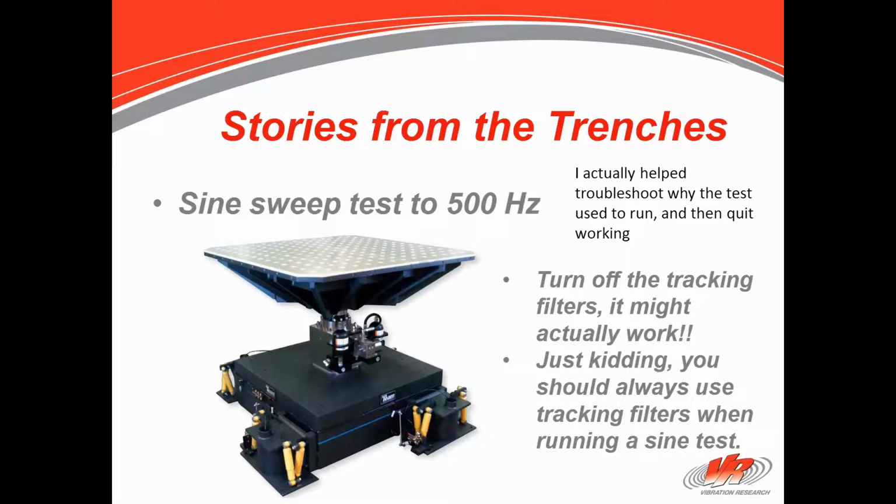So we talked about, well, how's your accelerometer mounted? Where is it? Do you have a product on it? What does your fixture look like? The usual resonance troubleshooting problems. Finally, I asked, what kind of shaker are you running this test on? Oh, they said, it's a hydraulic shaker. Really? A hydraulic shaker? How big is the head on it? Oh, it's a 6-foot head. And I'm thinking to myself, there is no way a hydraulic shaker can typically control to 500 hertz. It just can't be done.